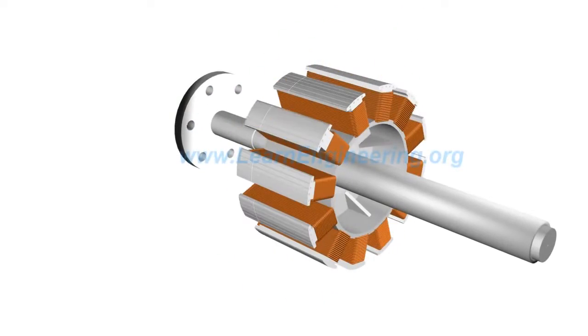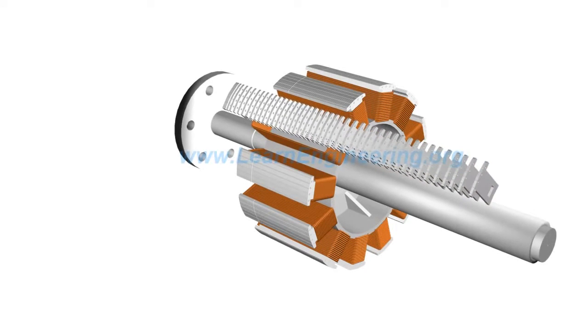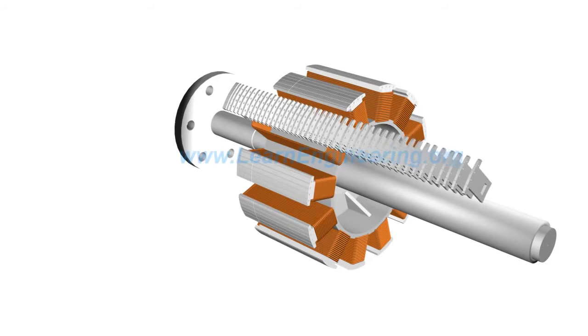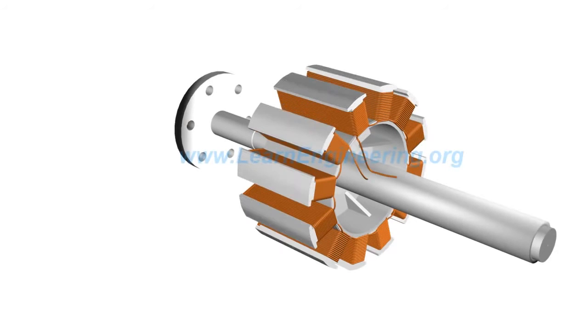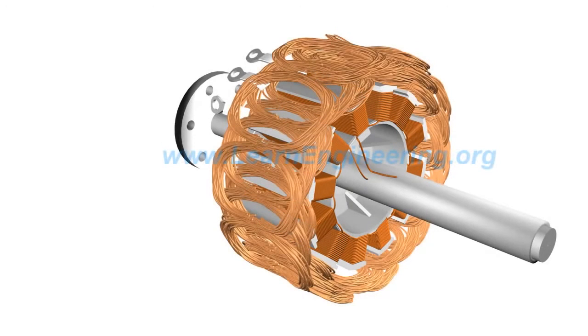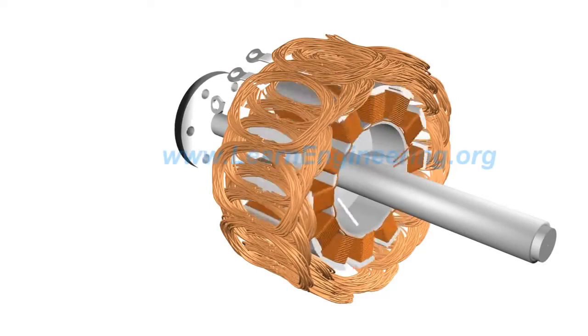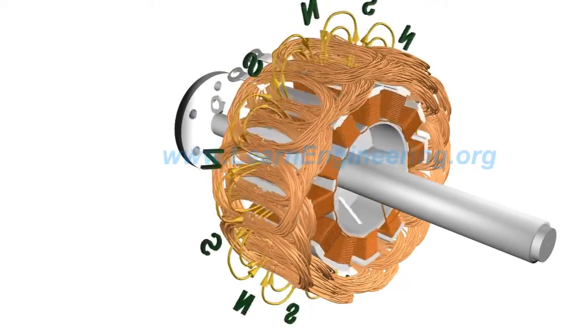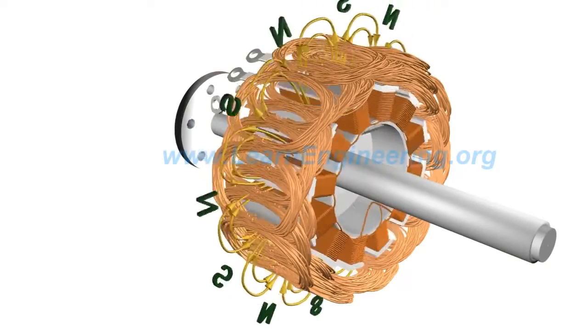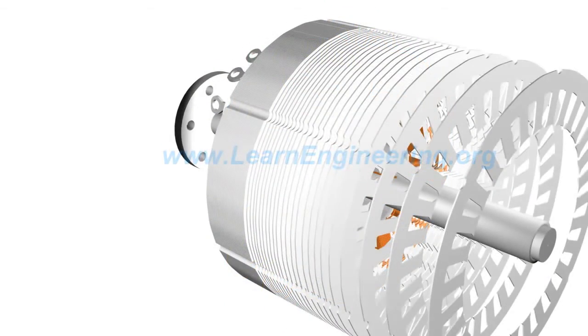Pole core is used to effectively transfer magnetic flux, and it is made with fairly thick steel lamina. Such insulated lamina reduces energy loss due to eddy current formation. Armature winding of a 3-phase, 12-pole system is shown here. A stator core is used to enhance magnetic flux transfer.